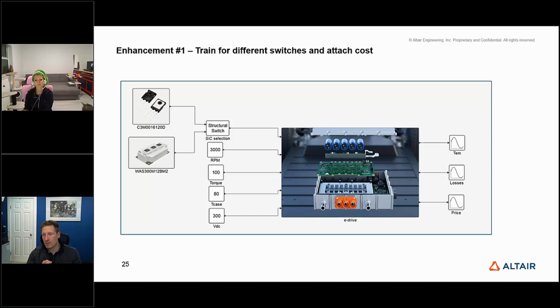The way you minimize inverter losses is more expensive switches, so silicon carbide or gallium nitride devices versus IGBTs. This is not something that FIRST kids have to deal with. It's only something you can optimize if you are designing your own inverter, which I'm not expecting many people will take on.